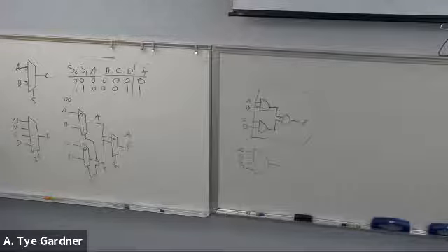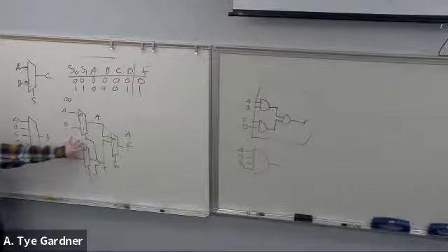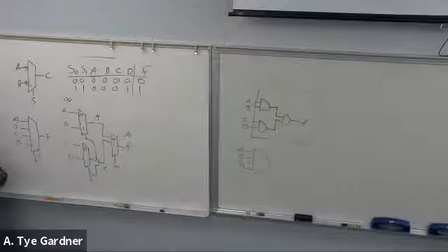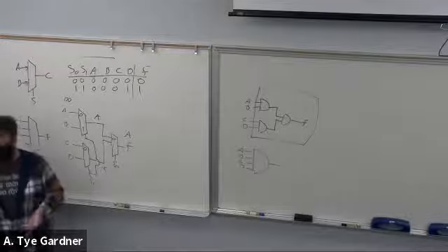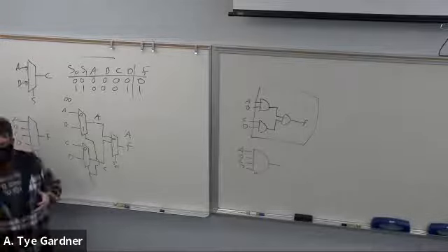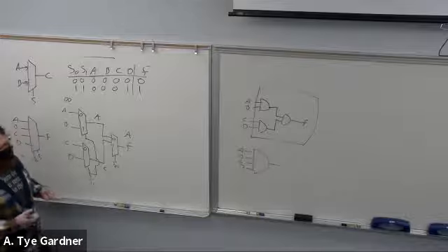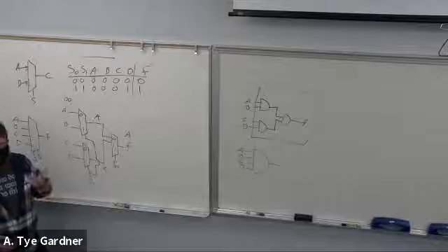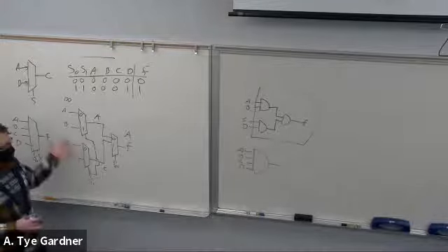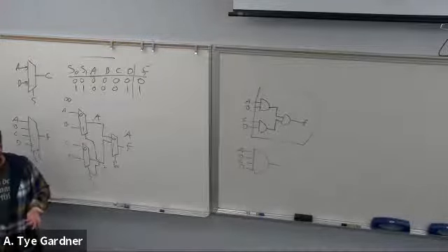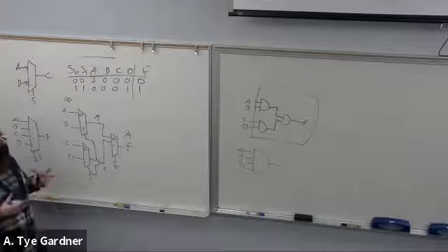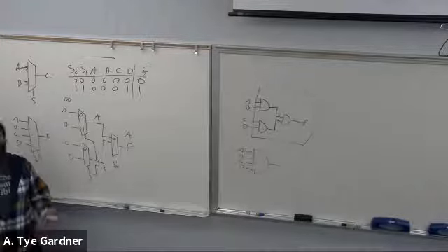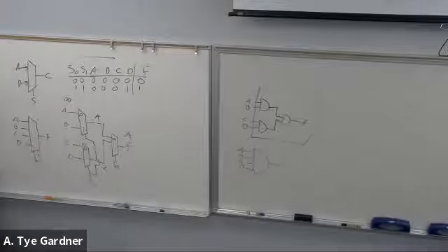Well, now it turns out you can actually design really complicated circuits using nothing but multiplexers. The book has a whole two sections or something on designing circuits with nothing but muxes. We're not going to cover that, but I want you to be aware that it exists. Part of this comes down to being cheap. Muxes are kind of big circuits, but if you have an integrated circuit that has nothing but muxes on it, it's easy to manufacture, easy, predictable and cheap. So while it ends up being a little bit big, it ends up being affordable. So there are reasons that you would want to use a mux-based design. We're not going to cover that. I just want you to be aware it exists.